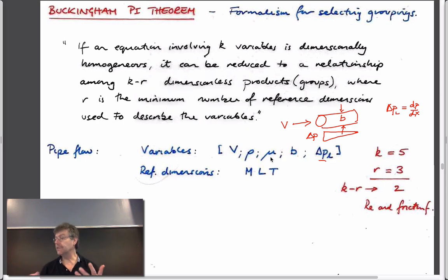So if we think those are the 5 parameters that completely describe this physical system, we could add more. We could have 10 parameters. It would just make our job a bit more cumbersome, and we'd find out that some of those extra parameters wouldn't make any difference. But we could add surface tension, for instance. You wouldn't think that would have a case in this single phase flow problem.